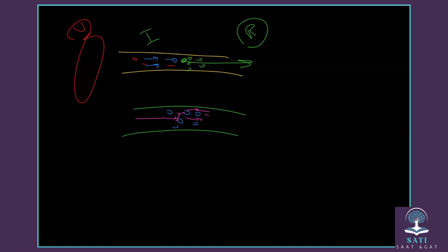The current is the number of charges that are moving in 1 second. So if they have higher speed, that means they have higher current. But due to many collisions of these electrons with the atoms, the speed will be less, that means it will be decreased. So the number of charges per 1 second will be decreased, so the current will decrease. So you understand now that resistance represents the amount of these collisions in stopping or interrupting the current from movement.